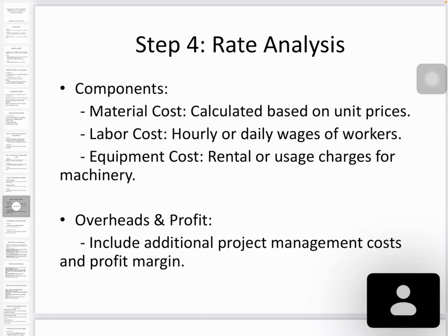Finally, after calculating the basic cost, you have to include your overhead and profit margin. So if the company managing director decides to go for this project with a 10% profit margin plus 10% overhead. Sometimes they will give the overhead and profit together, say go with a 25% profit and overhead margin.